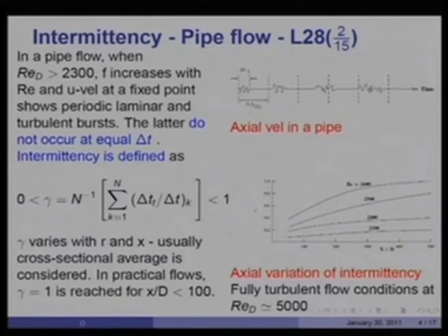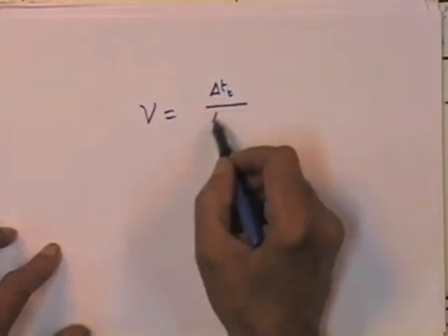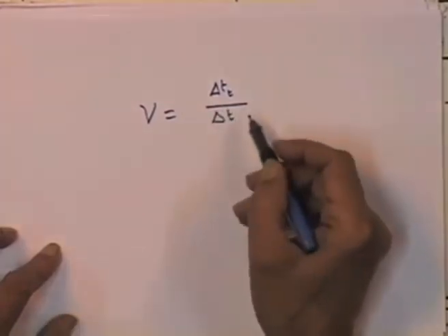then in each delta t, a small fraction of it, delta t sub t, would be occupied by a turbulent patch. Likewise, here this much would be the delta t t, whereas this is the total delta t. Now, we define intermittency as so. Intermittency itself is defined as gamma, delta t of turbulent patch divided by the total time step delta t, and